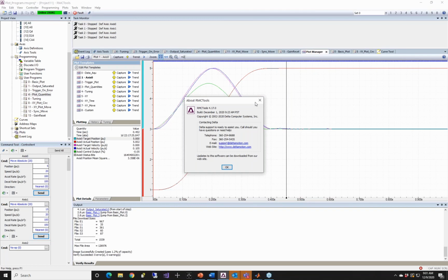For say pressing where we're synchronizing 4 axes together and they're all mechanically connected, we always are looking at the skew, and it's a good thing to monitor. Generally, there's kind of 2 ways that you can go about it. If you have 2 axes and they're trying to be synchronized together, say you're using a sync move, they're going to have the same target position. So if you're wanting to monitor the skew so that you can shut things off in case of an error condition, sometimes you need to do that.